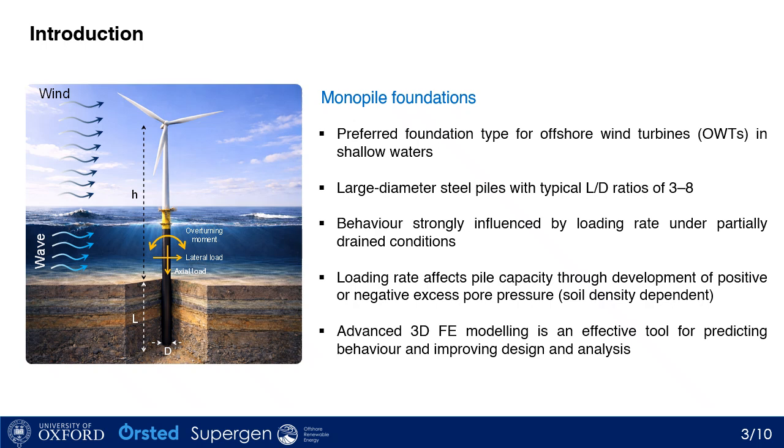Under this condition, the loading rate becomes very important, particularly in partially drained condition, where the soil response depends on how quickly the loads are applied. This can lead to development of positive or negative excess pore pressure, which in turn affects pile capacity significantly. In addition to laboratory and field testing, finite element modeling is a useful tool for understanding the behavior of monopile foundations and useful for the design and analysis of this structure in practice.